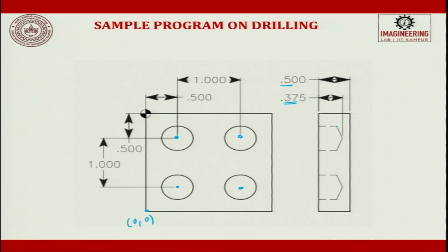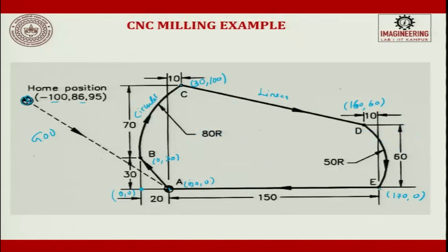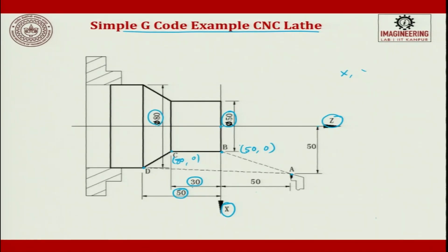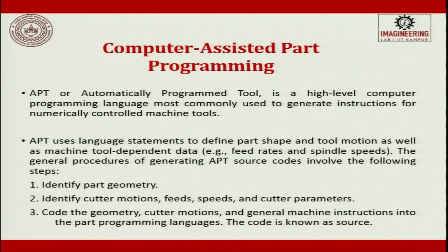So, since it is a drill, you will always have this conical taper. You should have a flat, but since you are drilling and it is blind, you will have this conical depth. So, the depth which is given here is 0.375. Here it is all in inches. Please try to execute the previous 2 programs and then this program, 3 programs, and then you can share it across, or if you have doubts you can keep it for yourself.